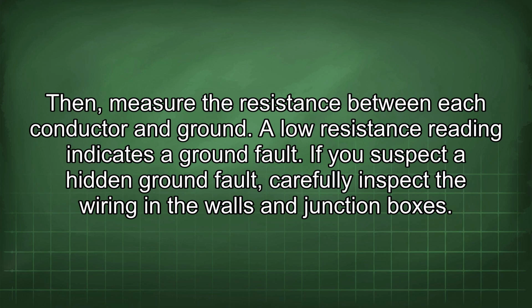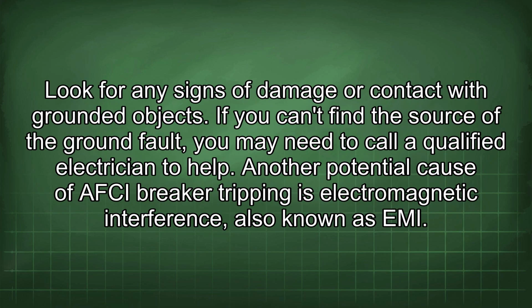If you suspect a hidden ground fault, carefully inspect the wiring in the walls and junction boxes. Look for any signs of damage or contact with grounded objects. If you can't find the source of the ground fault, you may need to call a qualified electrician to help.